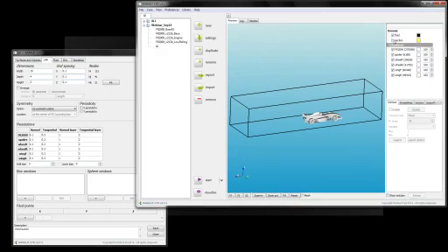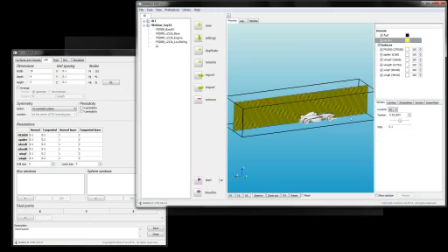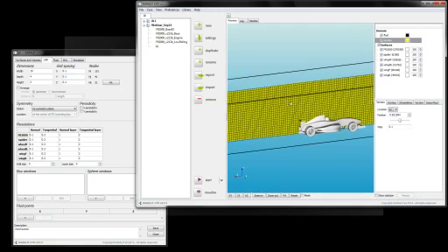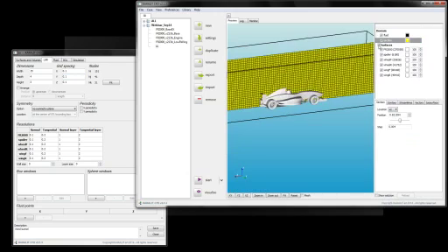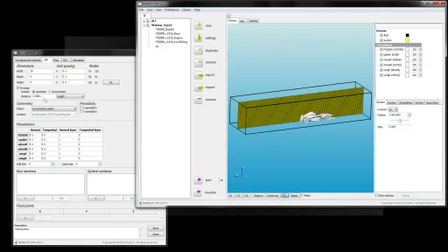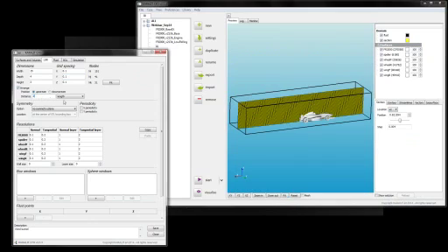So essentially, it's set up at the moment a coarse grid around the car, and notice that the grid is at the moment just set up in the whole block. So if I remove the surface there, you see the grid is protruding through it. I would also like to arrange that the domain would start 2 meters upstream of the car.